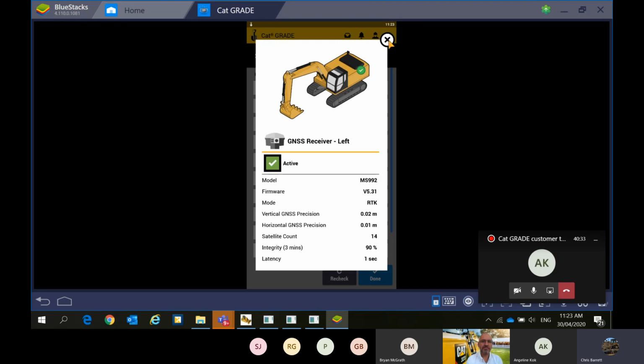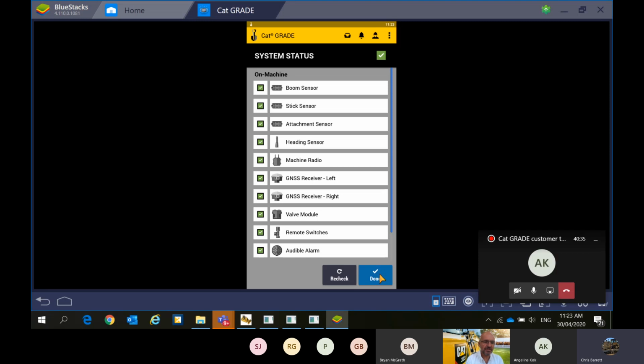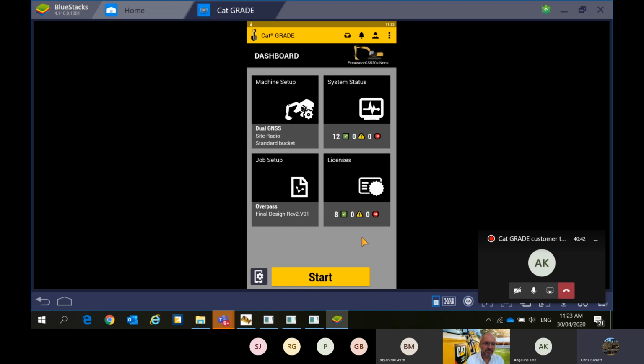Excellent. I should mention here that we are on a computer simulator, which has defaulted us to a UHF version in the US. For those that are unaware, in Australia and New Zealand we work off 450 megahertz, but this US one is at 900 megahertz, so don't get confused there. I just want to repeat, standard from factory, Caterpillar has a cellular product link that supports cellular correction. In other words, IBSS, internet base station, and VRS, your virtual reference station.